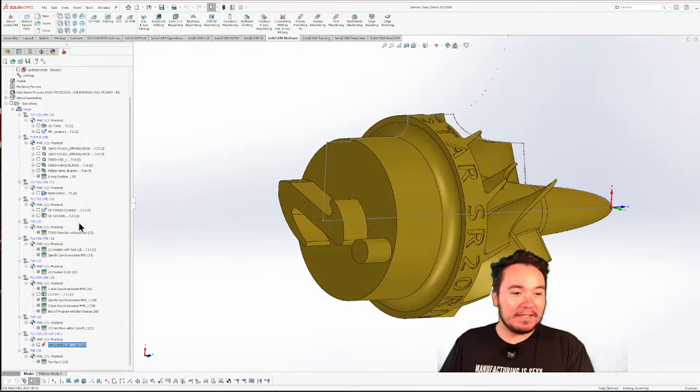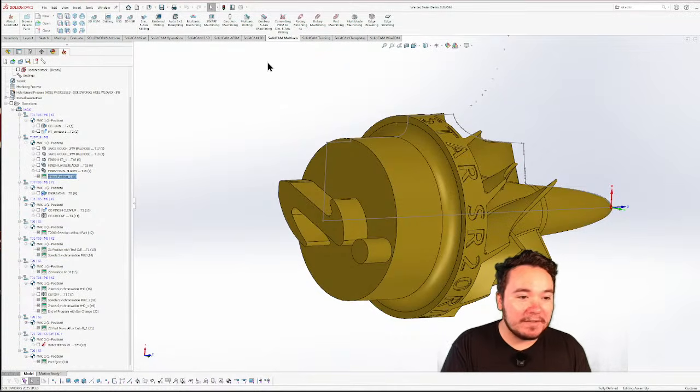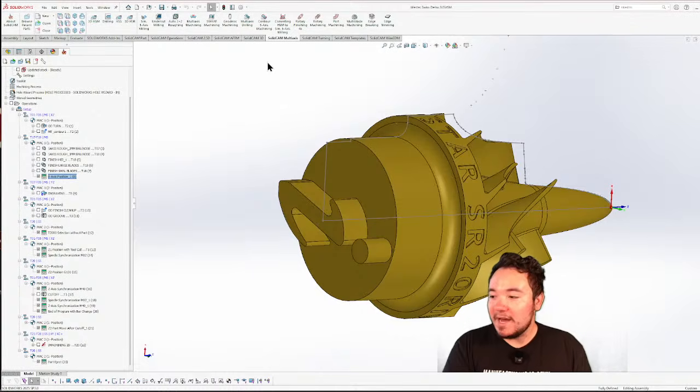Okay, so everything's calculated. I can show you, I entered an MCO in here, and that's B-axis position. So all it's doing is, after we're doing the 5-axis simultaneous cuts on the finished small blades, that was the last cut we did for the 5-axis simultaneous, I want to home the B-axis head.